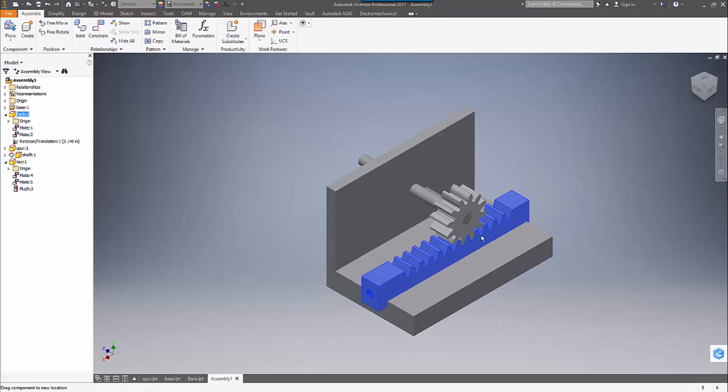Now, what happens if it doesn't move? Well, if it doesn't move, and it's frozen, what we have to do is look at what constraints we have that might make it freeze. And if it was moving freely all the way up to the rotation translation, then instead of the spur gear, try the shaft. If it doesn't move after you apply a specific dimension or specific constraint, then you know that that's the culprit of the movement. So don't go putting a bunch of constraints. Test it every so often to see if things still move. And once you put the rotation translation, they'll mesh.